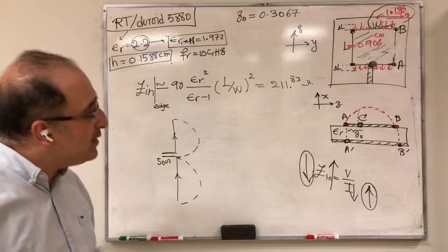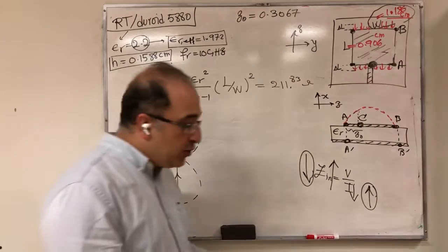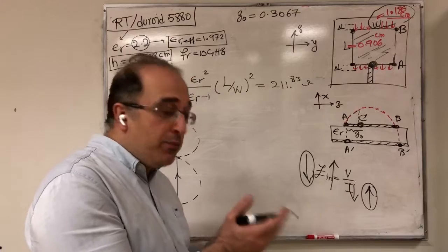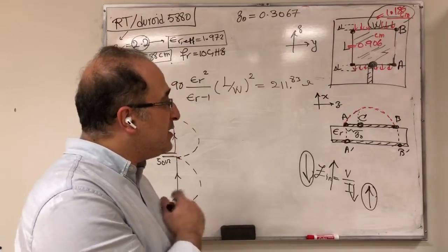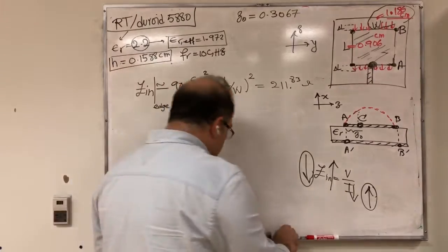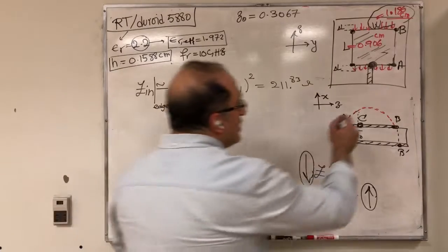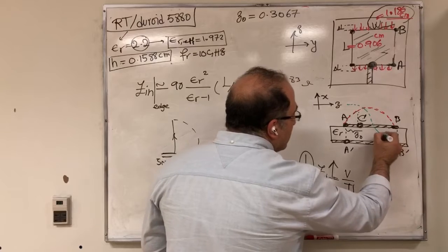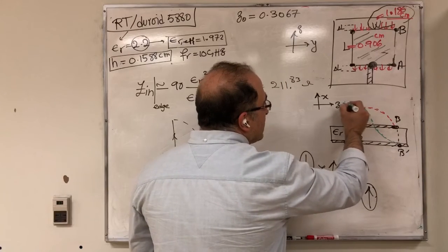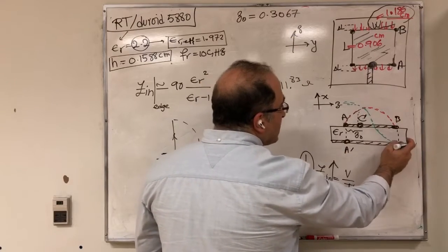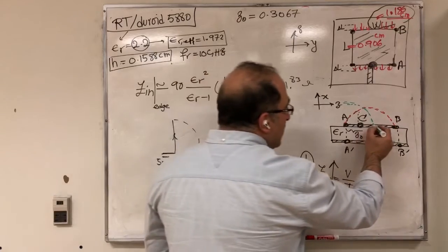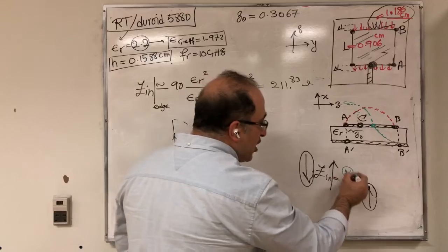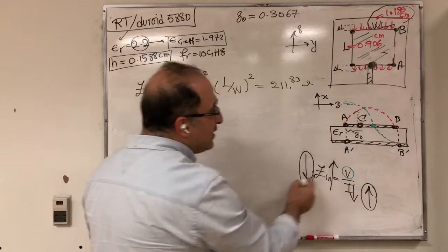Something also interesting here is that if you look at your voltage distribution, based on the model that we discussed in the previous lecture, voltage distribution does this variation. So it's maximum here with the opposite polarity, but then zero at the center. So if voltage becomes zero, you realize that Z in becomes zero.